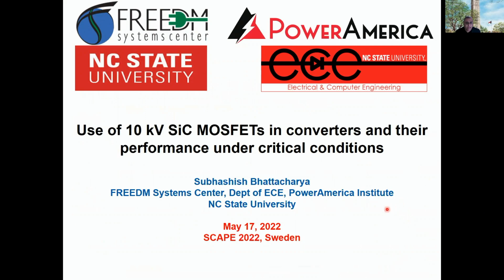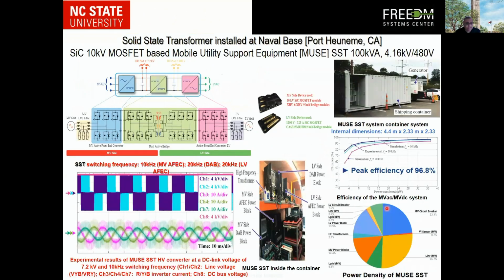As a first step, I would like to present the use of the 10 kV MOSFET for a solid state transformer. This is a project which we did for the Navy, where we delivered a 100 kVA, 4160 volt to 480 volt solid state transformer with 10 kV MOSFETs to the Navy in this container. And this is installed at a naval base. So the SST that we delivered is based on 10 kV MOSFETs.